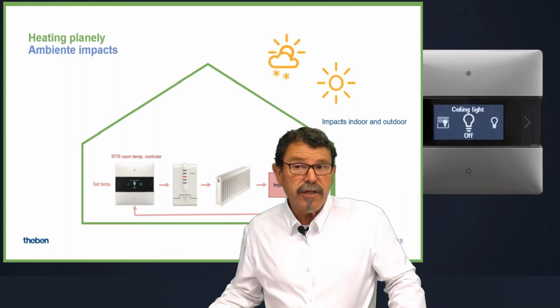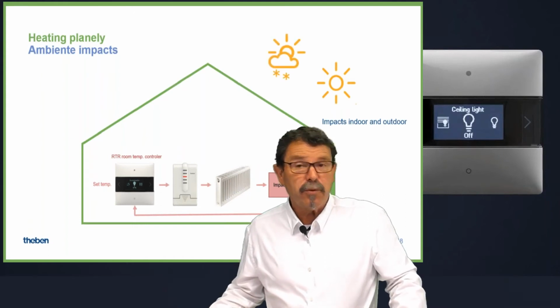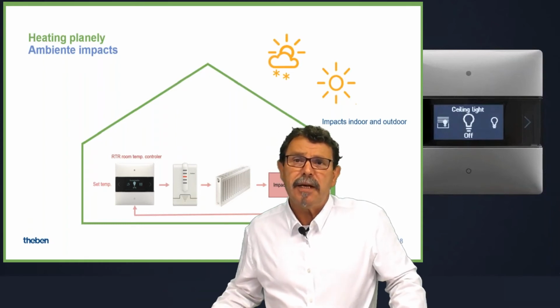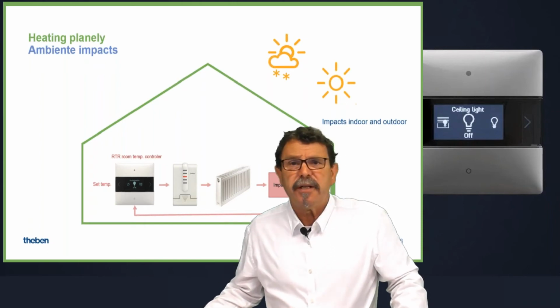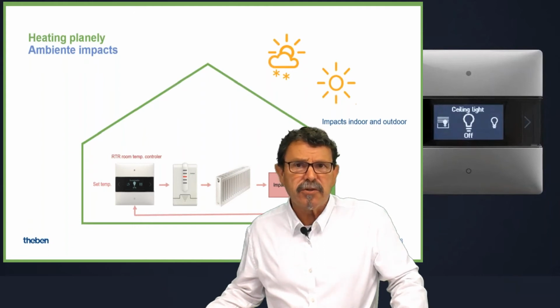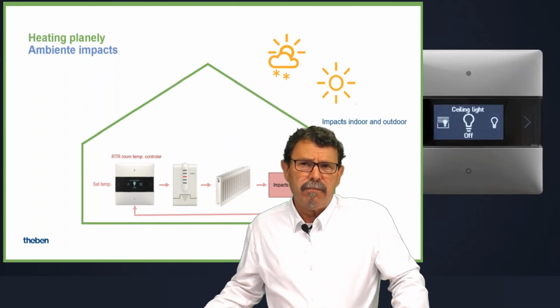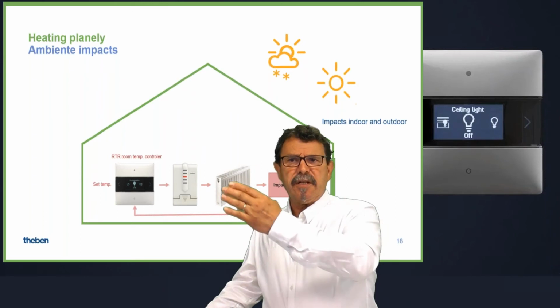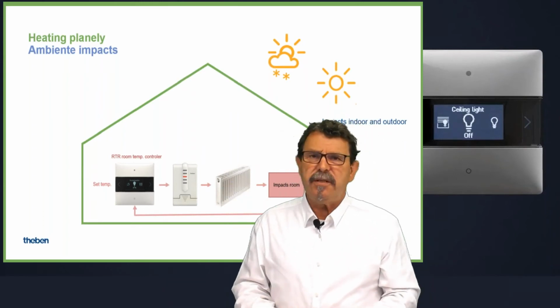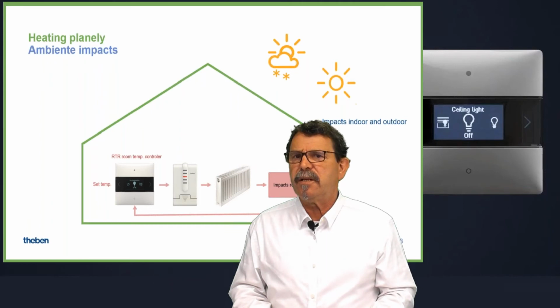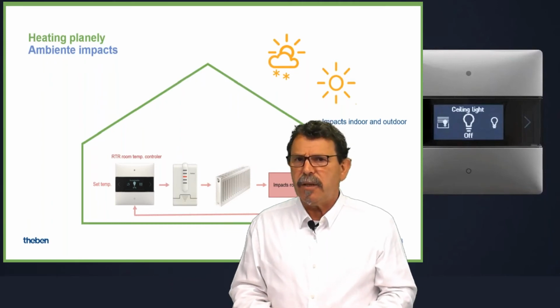And for that purpose, you need a powerful controller, which is absolutely flexible in its control application. We support PWM control and, if you like, hysteresis control. Frankly speaking, when we talk about split units, heating and cooling systems, it is always recommended to use PWM control.